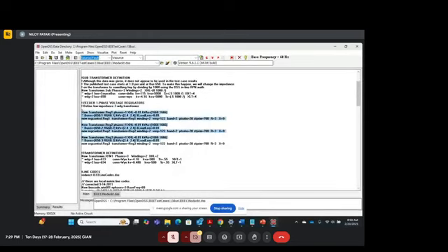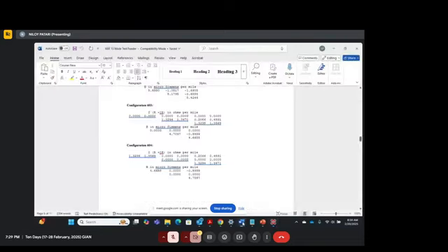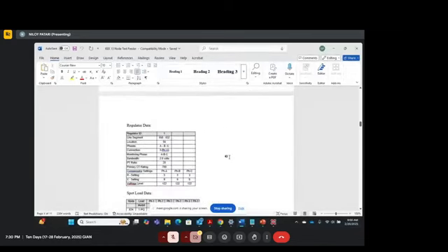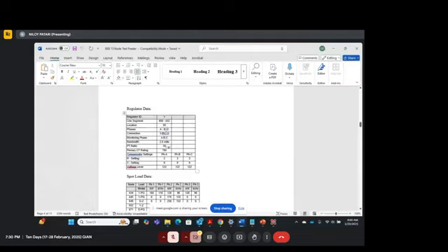And then you have the regulators defined, right? This is regulator 1, regulator 2, regulator 3. Regulator 1 is connected from 650 to RG60, right? Suppose I show you what this actually means. You have this regulator data, which has 650 to 632. It says where the regulator is placed.